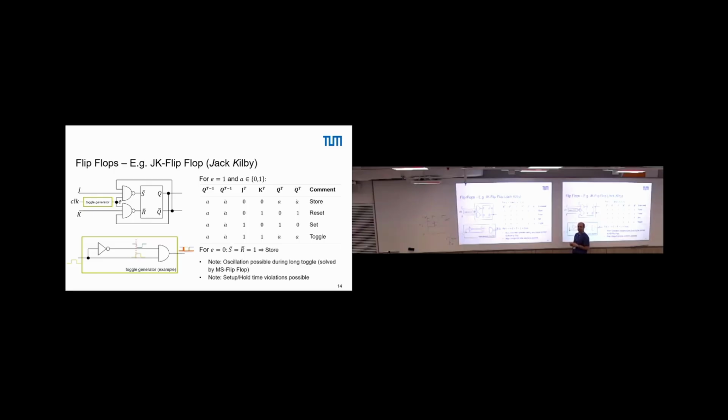What does this change? So, effectively, we have the same structure as before. We have this RS latch. Yeah? So the RS latch was, we have two NAND gates, cross-coupled, and here the connect. And on top of this, now there is an additional feedback from Q to R bar and from Q bar to S bar.